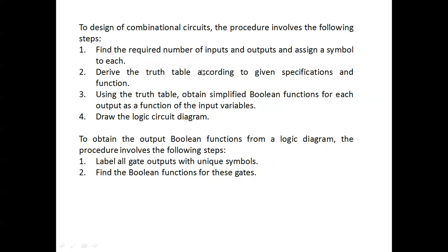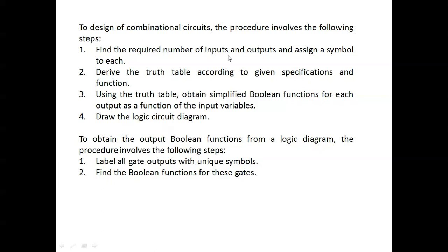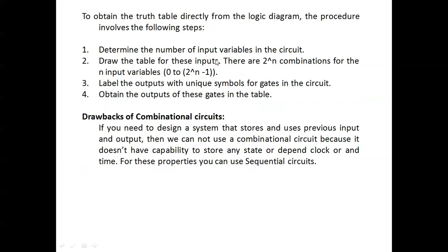Find the requirement, inputs and outputs. Draw the truth table, and using the truth table obtain the simplified Boolean function and draw the circuit diagram. So these are the procedure we have to follow to obtain the truth table and the design.